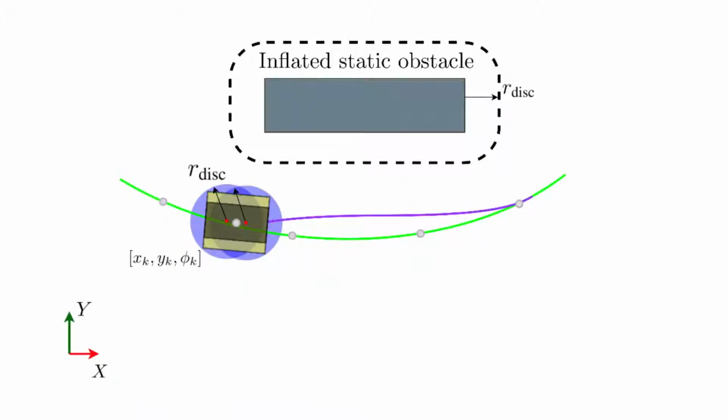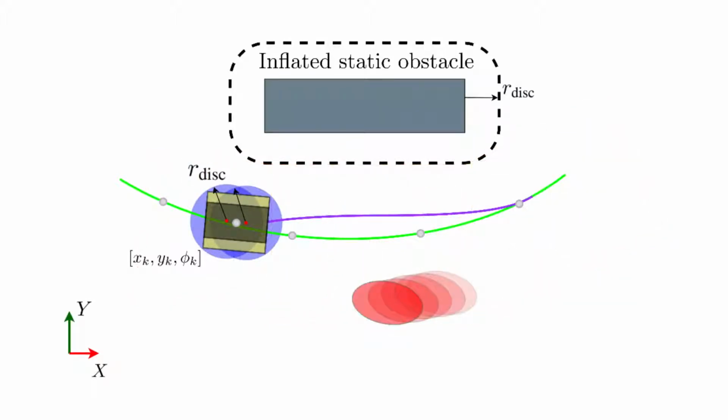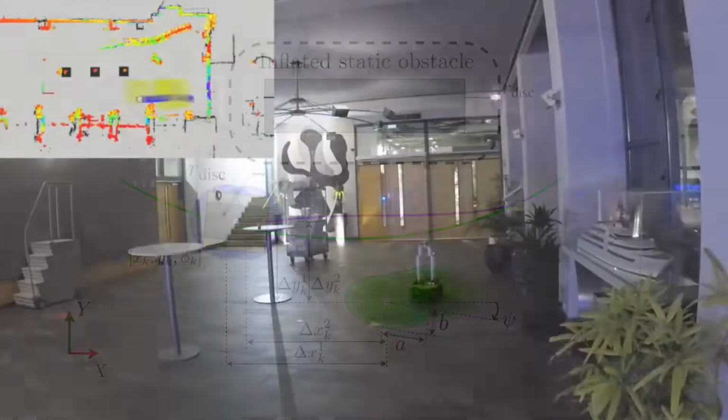In order to avoid collision with the static environment, a polygon convex region in free space is computed for each prediction step. Each ellipsoid dynamic obstacle is enlarged such that we can prove that our collision constraint with respect to the vehicle representing disks entirely bounds the collision space. Additional clearance from moving obstacles is created with a repulsive cost term.